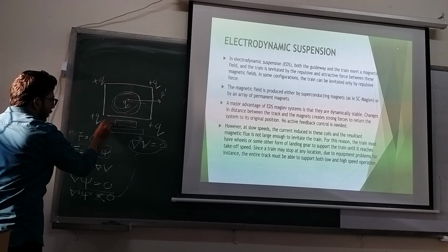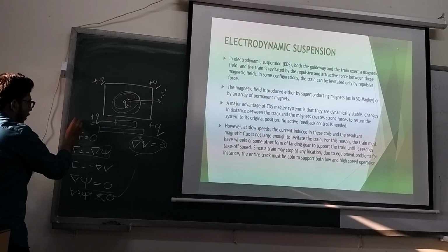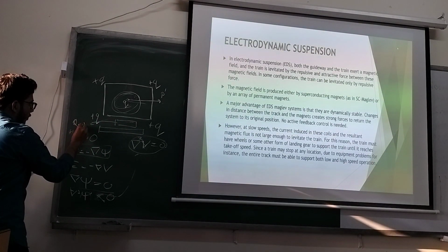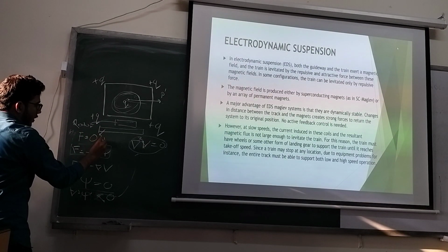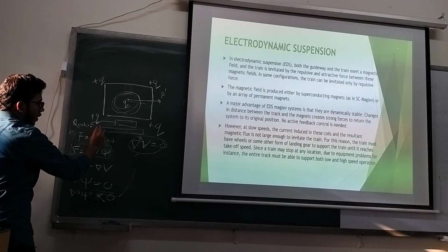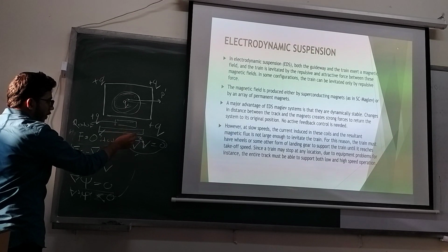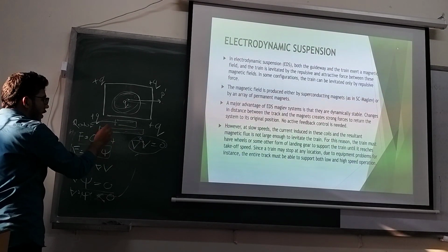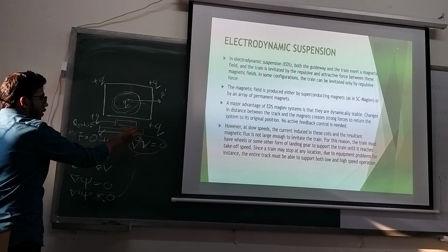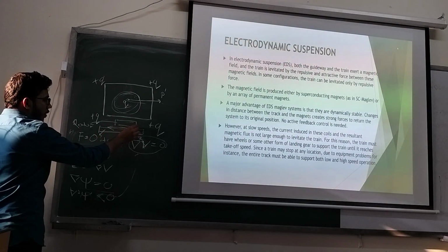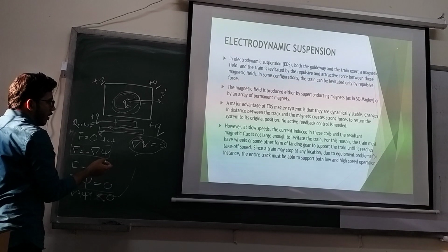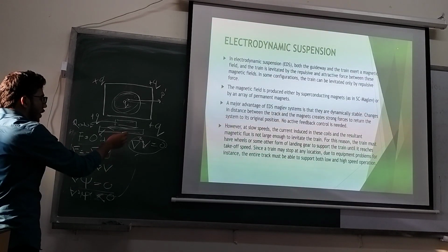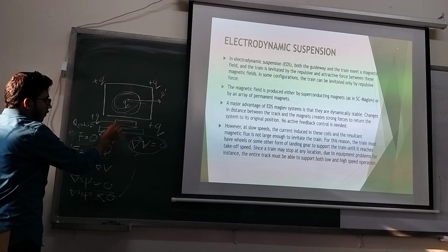So, this is the general construction of a linear motor, right? We can consider this part as the rotor, and this part is the stator, which has the three-phase power supply. The combined effect is in a linear direction, so it produces a magnetic field that propels the rotor in a linear way.